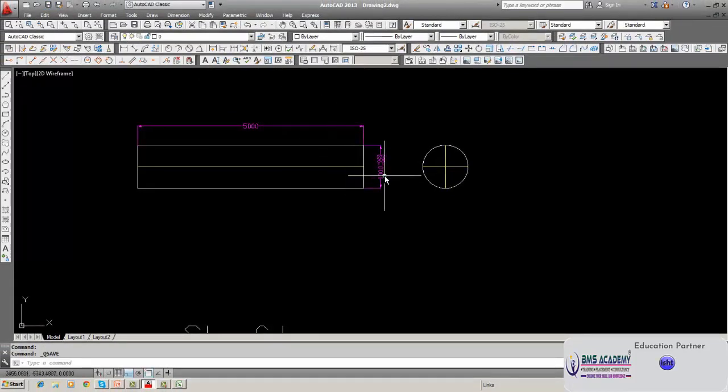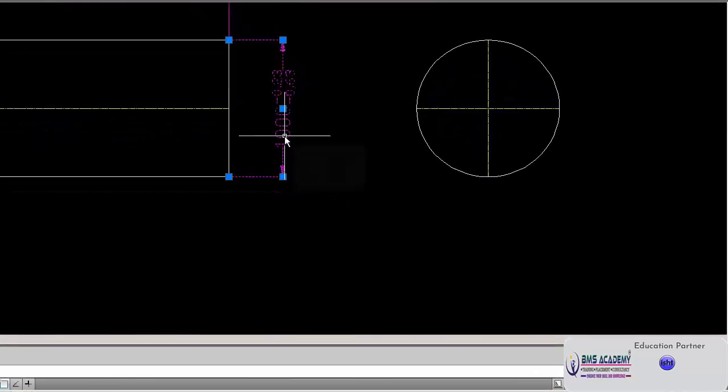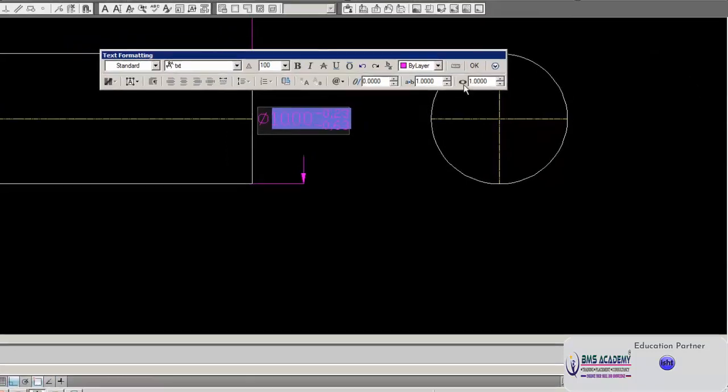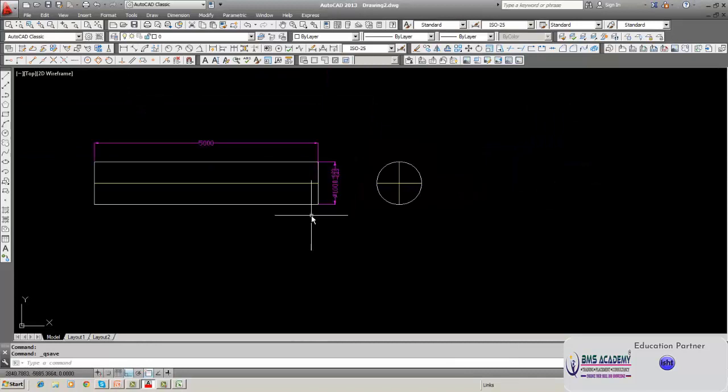This is how we can do it. And here, this is a diameter. For indication of the diameter, what we have to do is you write 5. So like this, you put a value, you put a symbol, percentage twice, see, it is 5. So this indicates the diameter. This is how the shaft OD is dimensioned.